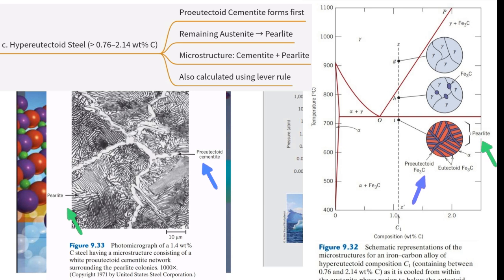That's the one. Looking at the micrograph, it might look superficially similar to the hypoeutectoid structure, but instead of those larger light areas being soft ferrite, you'd see networks or maybe thicker layers of the hard, often light-etching proeutectoid cementite surrounding the darker striped pearlite patches. That's a very good description. The two microconstituents are proeutectoid cementite and pearlite.